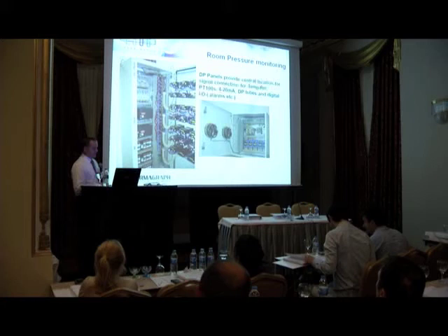So it's something to consider if you're writing a URS to have a look at the manufacturer's data, because a lot of people put a specification of 0 to 100%, and unless you're going to spend a huge amount of money, there isn't a sensor out there that's going to do that for you.